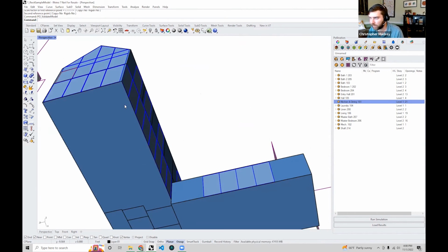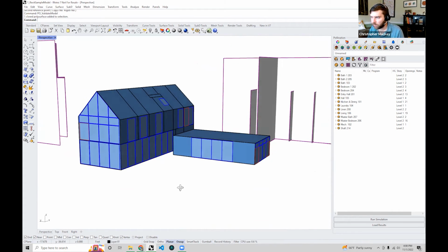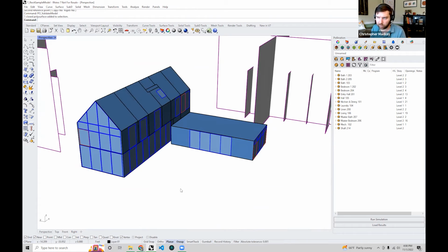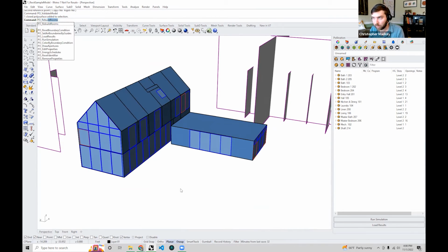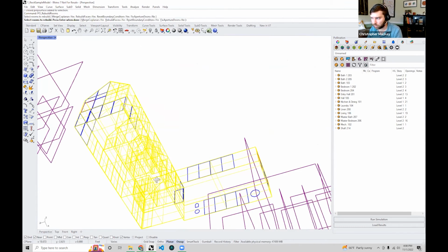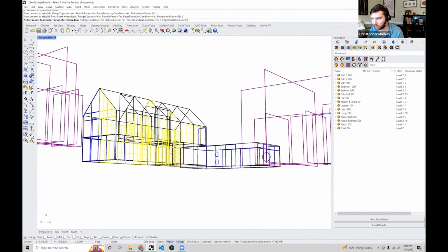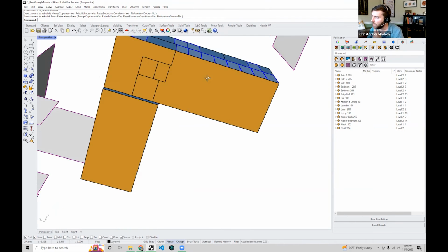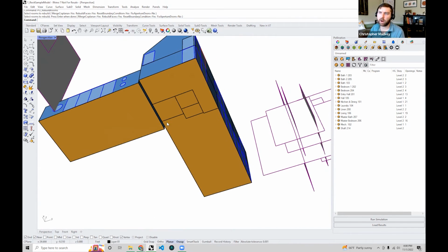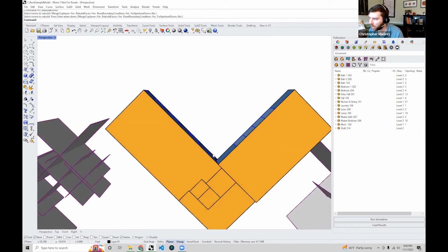So I noticed that, in the process of doing this, maybe we lost the ground boundary conditions. If I do want to reset those ground boundary conditions, I can just do PO rebuild rooms again and just select everything. This will help me reset those ground boundary conditions, because it looks like all these got selected to the ground. Maybe we somehow lost those when we aligned to the grid, it must have reset them or something like that. But this looks good now.